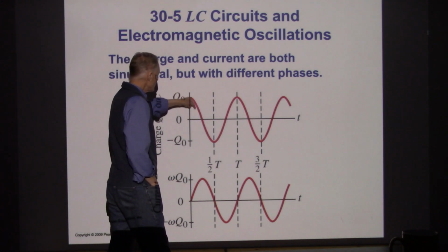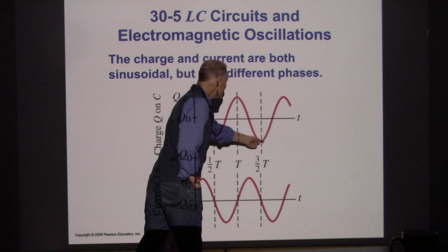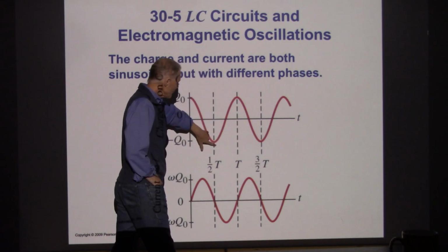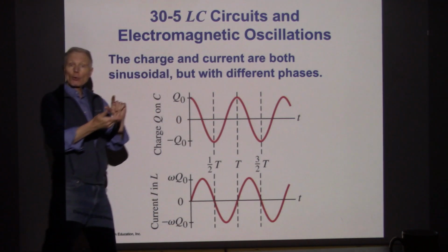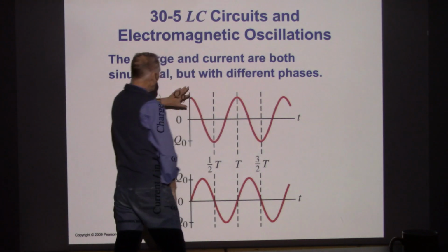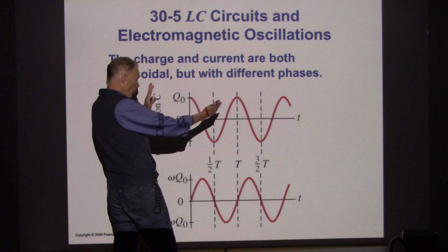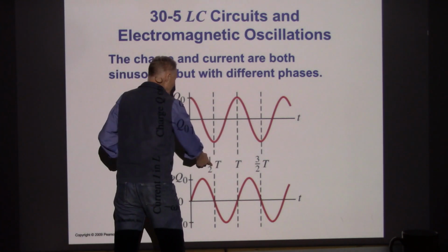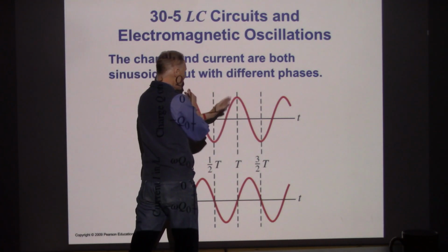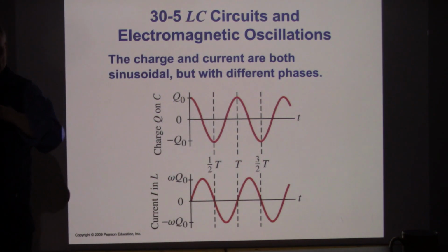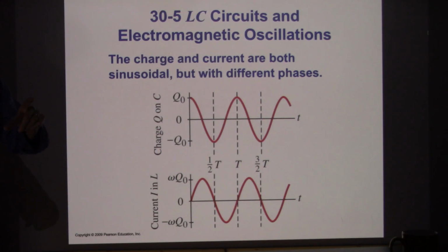So here's what the charge in the capacitor looks like. Now what you can see is that it's just cycling. That is, 1/2 of a cycle completely reverses the charge on the capacitor. And then a full cycle would be going from the capacitor fully charged with one particular charge orientation. It reversed at half period, and then it reverses again, and it's back to the same. The plate that was negatively charged is now positively charged, as when we started out.